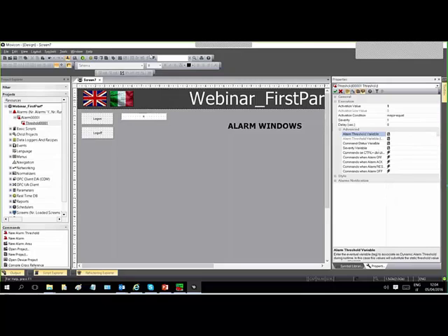Instead of writing a fixed value, you could add an alarm threshold variable, so the level could be dynamic according to this second variable. You could set a command when you double click on the alarm window on a specific alarm: perform an action, open a help, up to you.